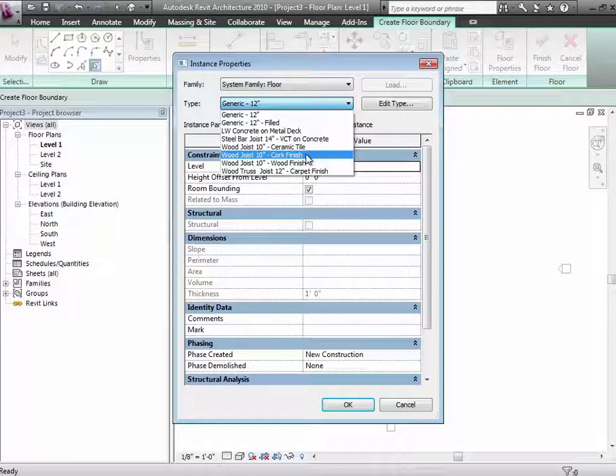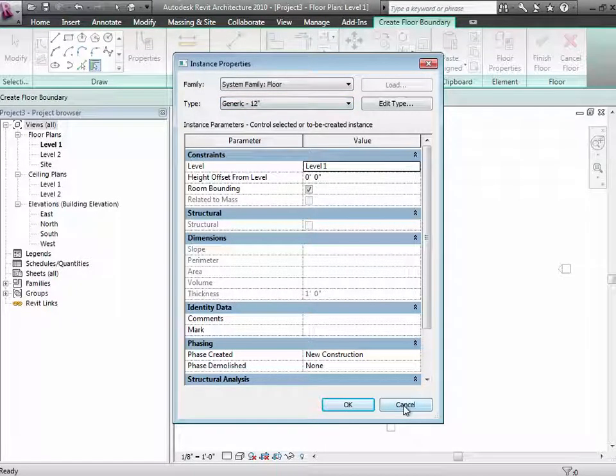So get used to the idea. Some things we save out, component families we save and then reload. But these system families, you can even tell it's a system family. It says so there. Okay, you use transfer project standards to get them across. That probably won't affect you anytime in assignment 1. It'll hit you later on in the quarter when you really want to use something. I defined the perfect thing back in assignment 1 and I'd like to use it again in assignment 3. So you go harvesting out the parts you like from assignment 1 and pull them across.